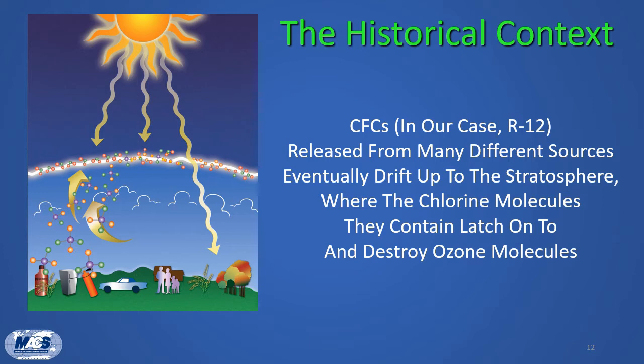Before the 1990s, it was common practice to just add refrigerant to leaking systems. It was also common practice to vent the entire refrigerant charge to the atmosphere if the system required any type of service which involved opening the refrigerant circuit. These practices were acceptable because refrigerant was relatively inexpensive and thought to be environmentally benign. But knowing what we do today about the role of CFC-12 in the degradation of the Earth's protective ozone layer and the potential of global warming, venting refrigerants is irresponsible and is not permitted.